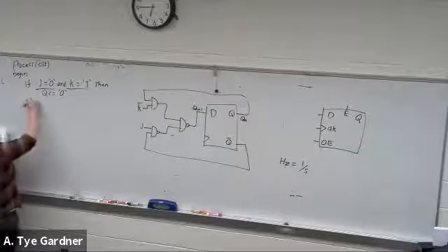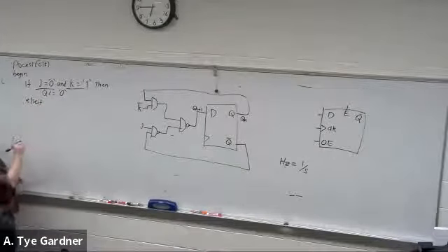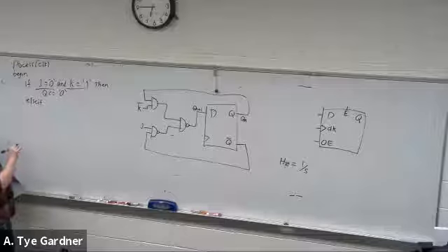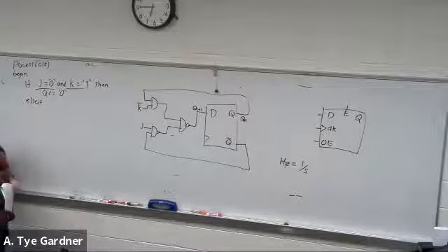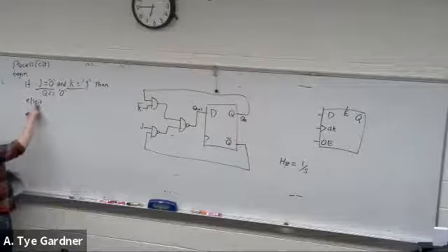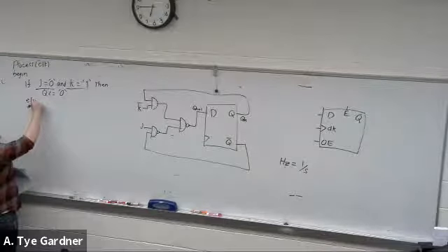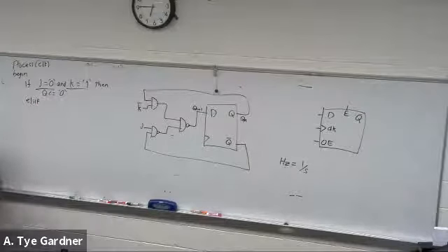And then you can do else if. There's an annoying thing with VHDL where when you write the else if, there's no E in there. It is no space elsif. I don't know why they decided to do that, but they did.